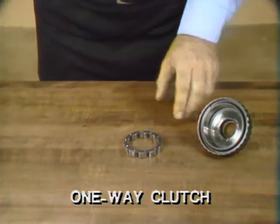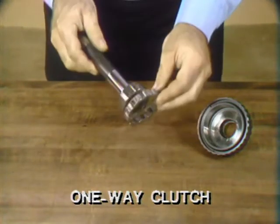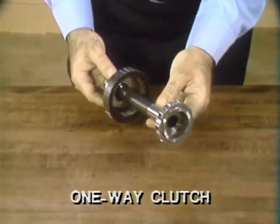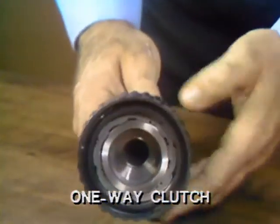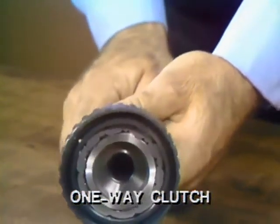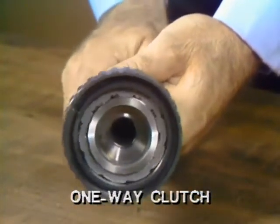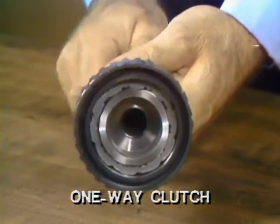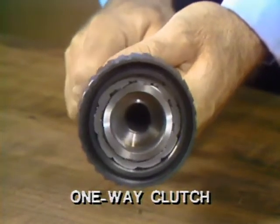For demonstration, we have removed the direct clutch cylinder from another turbine shaft, so we can see the one-way clutch in detail. Now, Joe is putting the clutch pieces together so that the roller assembly is positioned inside of the outer race. Watch the action. Driving the turbine shaft causes the clutch to lock up, and this turns the low reverse sun gear at turbine speed.